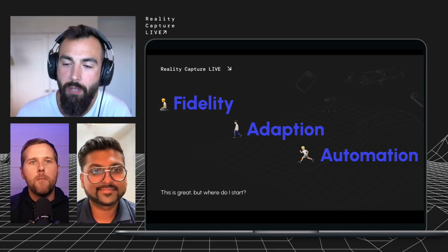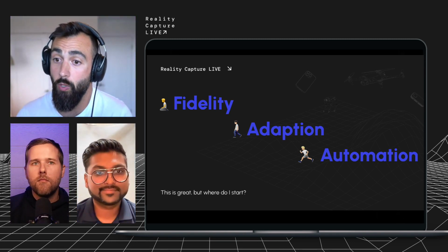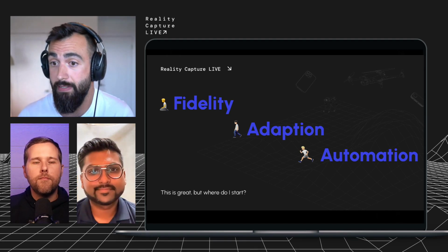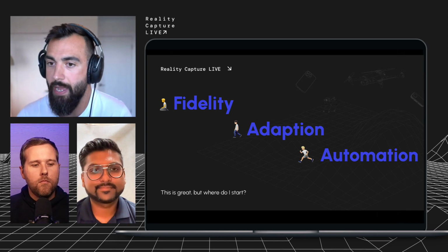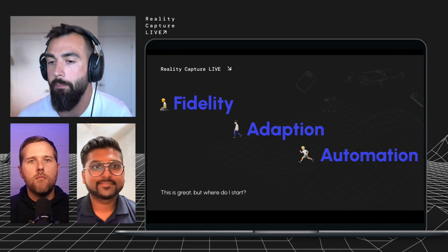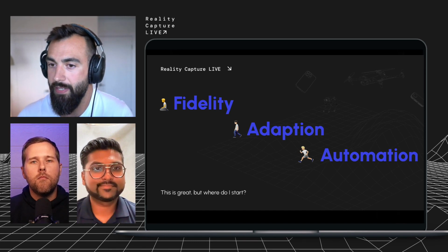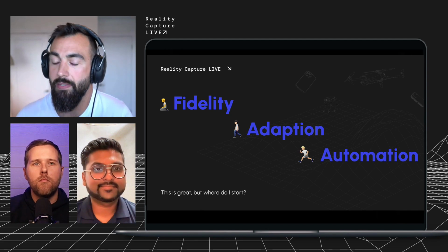Yeah, I put that first. What I mean by that is, are we sure that what we're looking for is going to come up in the data that we collect? A common one is cracks. Of course, we're looking for sub-millimeter detail. It doesn't mean you can take a picture from any angle with lots of megapixels and still see that crack.